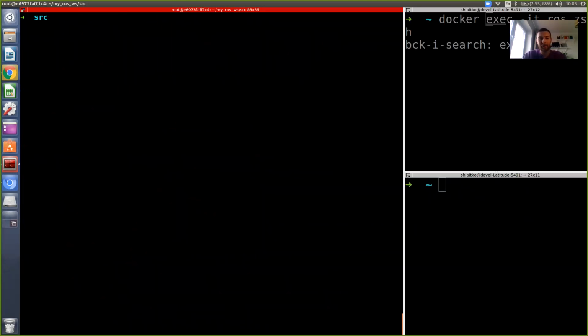We can do it afterwards just by modifying the package.xml file, because we know that this command just creates a package.xml and CMake file for us, in which it already includes these dependencies we specified. We can do it all manually afterwards, and actually advanced ROS developers usually do it manually. But for now, it's really simple for us to ask this command to do everything instead of us.